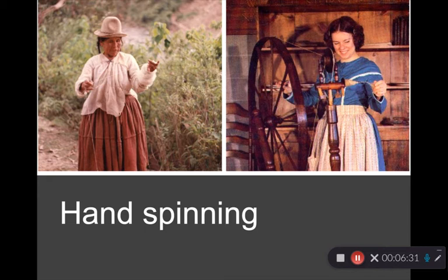As we said, staple fibers make spun yarns. Compared to your smooth filament or even your bulked filament, spun yarns tend to have a more fuzzy surface, and they need more twist to keep them together, because you have very small parts being put together. So you need a lot of twist along the length of it. Those fibers are less parallel, so it's duller and not as smooth as you'd see with a filament yarn. They can be weaker yarns, but they're also warmer yarns and sometimes much more comfortable next to the body.